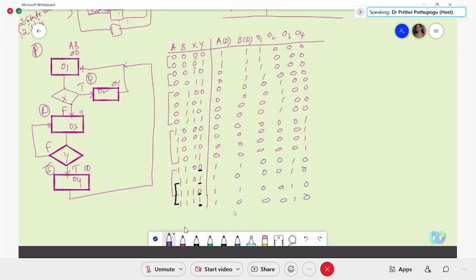But see here, this implementation is very simple once you define this table completely. There won't be any possibility of reduction, or you cannot visualize this in a less complex or minimized form. The complete table will be there if it is ROM based.